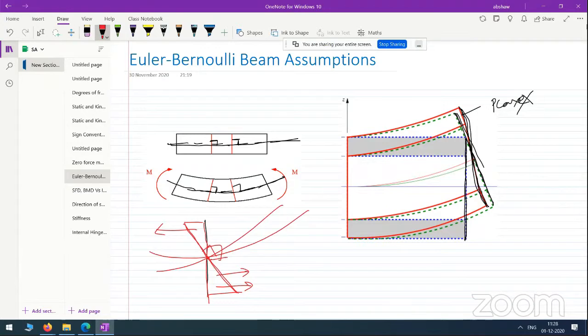Now, due to this assumption, the longitudinal strain across the depth of the beam can be taken as linear. This is the linear strain. Otherwise, the longitudinal strain cannot be. You will see this when next semester we study design of RC structures. In that case, you will see that these assumptions make all the derivations very straightforward. Okay, so this is the physicality of the assumption.